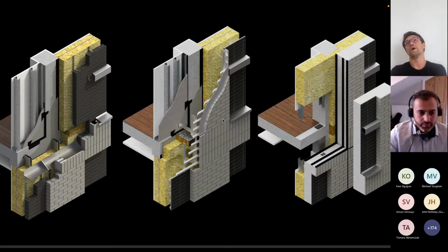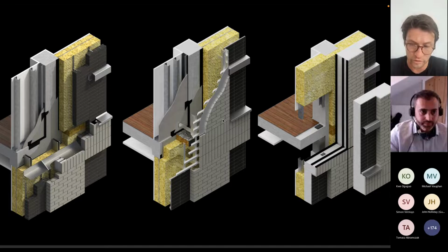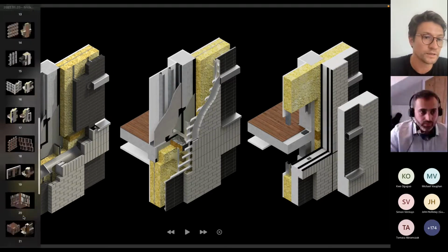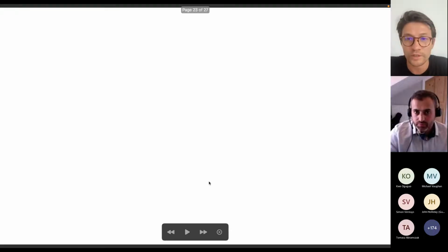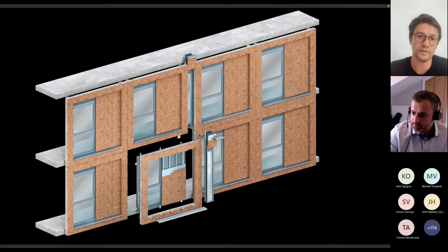But there is always a facade engineer's performance specification on high-rise buildings. It tends to prescribe more onerous tests. For example, on the building that was shown, because it's not a really standard precast concrete arrangement, a CWCT Sequence B test was carried out for that particular assembly, because it is a bit of a bespoke thing.